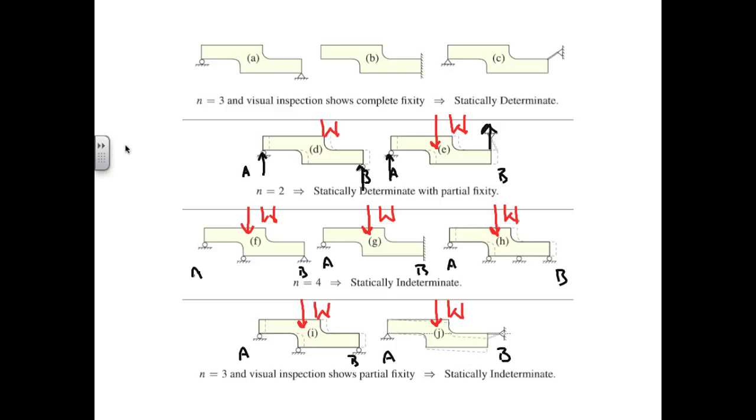Also, just as in case C, this is predicated on the cable being in tension. If the force applied is from below and the cable goes slack, N is reduced to 1 and the body can undergo both rigid body translation in x as well as rotation about the roller support at A. Cases F, G, and H all represent statically indeterminate support configurations.